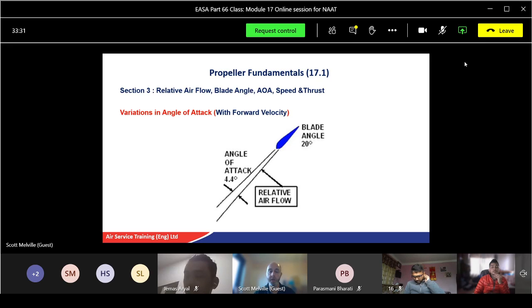It's like going up your gears in your motorbike or your car. You don't just drive about in first gear all the time. Maybe you do, maybe on the wheelies and that sort of thing. You will change gear, so the engine isn't going really, really fast. We don't have gears in the aircraft, but we can change the pitch of the blade to let the engine cruise once we get the forward speed of the aircraft.